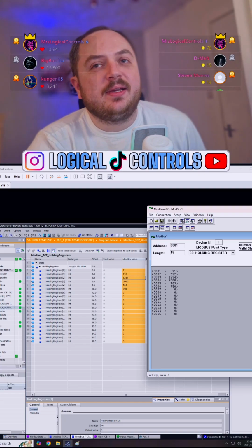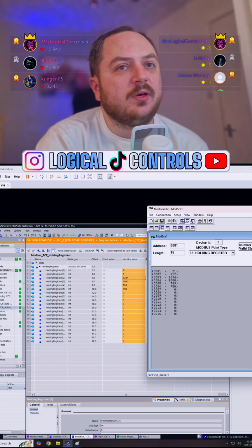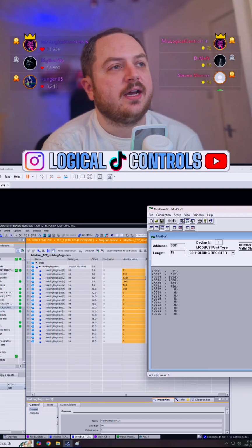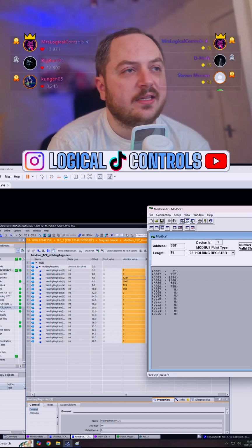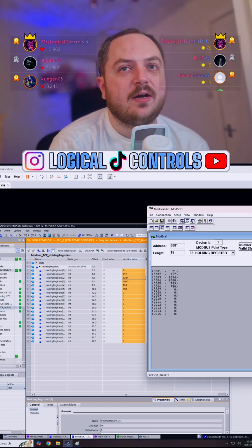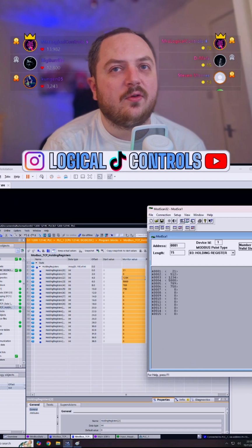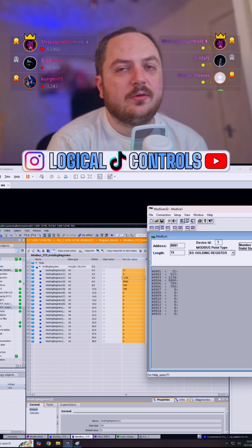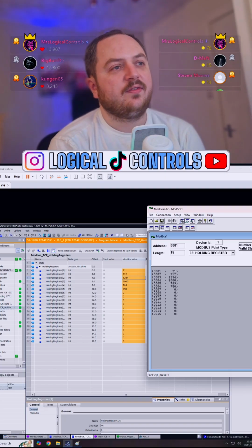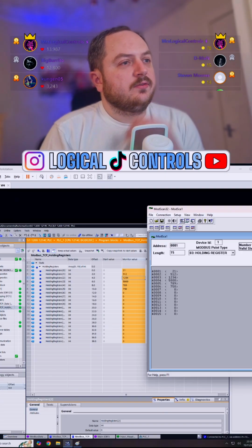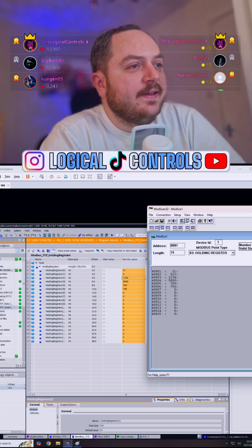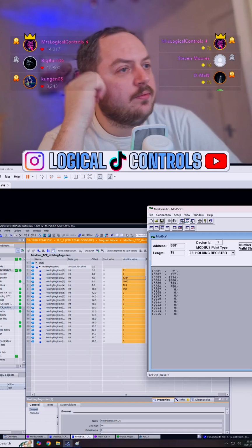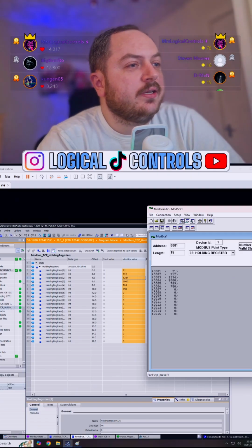Yeah, I see what you're saying, PB. You're right. A lot of people don't like the comms, but a lot of the time they're only really asking for trivial alarms and stuff like that. So it's not going to affect the system in any way if the Modbus went down to the BMS. But you're right, if Vault 3 goes to the BMS, and that BMS is on its own industrial network protocol, whatever, if that went down, they lose it anyway. So it doesn't really matter. Yeah, so long story short, they were the 2 that came to mind when you asked that question. Appreciate the question though, buddy.